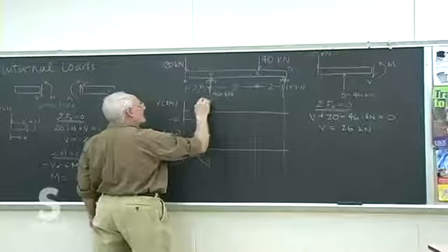All the down forces, V plus 20 plus 40, equal all the up forces, 46 kilonewtons. And so we solve for V there. Let's see, that's 60, goes over, becomes minus, what, minus 14? I think, yep. Which it should be, because we finish with a support of 14 over there.